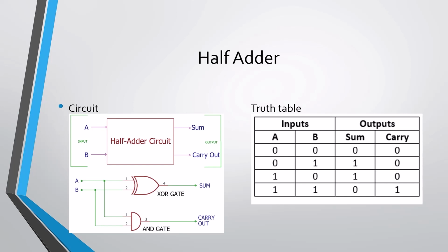half adder. Half adder is a combinational logic circuit which is designed by connecting one XOR gate and one AND gate. The half adder circuit has two inputs A and B, which add two input digits and generates a carry and a sum. The output obtained from the XOR gate is the sum of the numbers, while that obtained by the AND gate is the carry. There will be no forwarding of carry addition because there is no logic gate to process that.